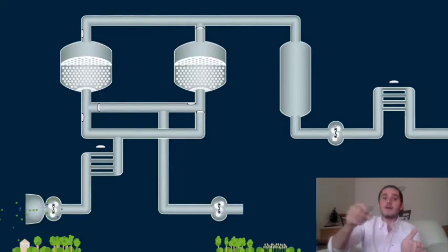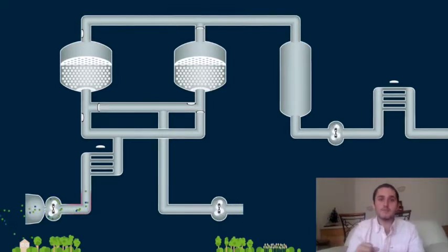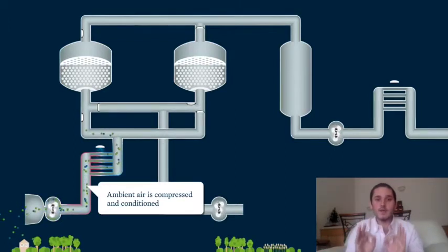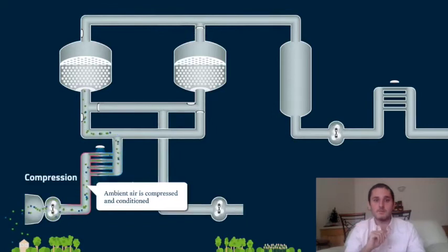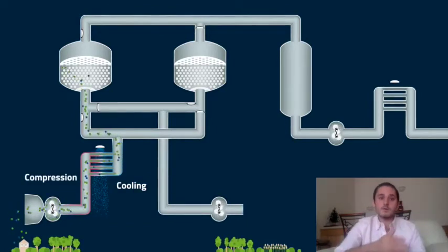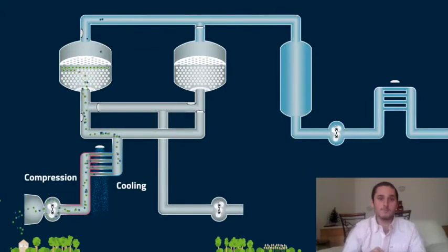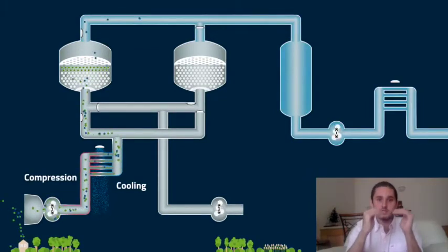leading the flow directly into a first tank. Inside of this tank, there are little spheres of a material called zeolite. This is a really good adsorbent in the case of nitrogen. Now, as you can see, while the flow remains, only the oxygen part remains flowing, while the nitrogen part remains inside of the first tank.